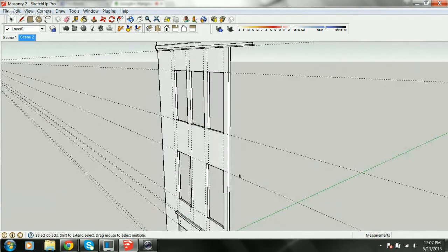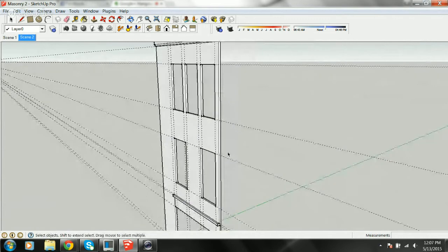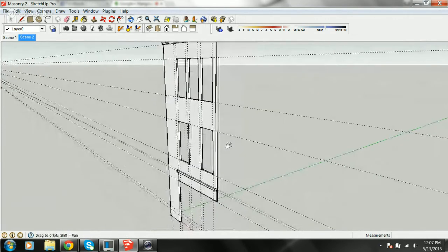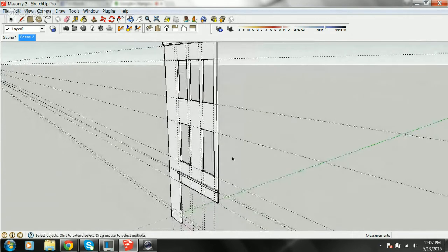Okay. And there are other shortcuts that we can go over at another time. I won't get into it on this segment about components. I can create a component. If I have a component for this window, say I just do this, but I create what we call a component. So it's going to include the brick cornice, it's going to include the window frames, and it's going to include, we'll say, a little latch detail for the inside because we're going to take it to that level. I group all those within a component, which is a group.